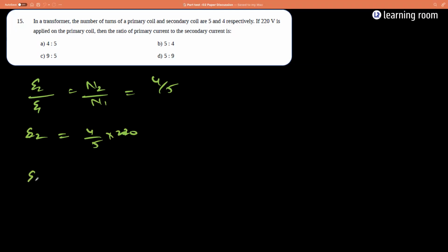So what do I write? E2 by E1 is equal to N2 by N1. Is this not equal to I1 by I2? Correct? Because E1 I1 is equal to E2 I2.